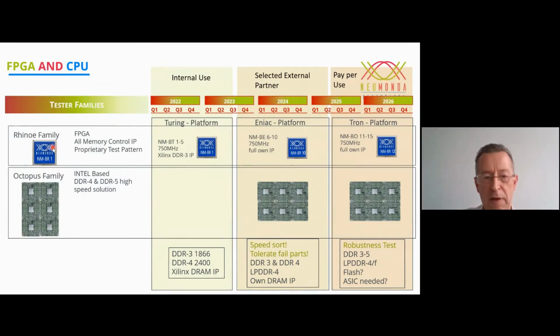If you do motherboard testing with a CPU, there is a microcontroller, the memory controller, controlling the memory channel. So the pattern you write, you don't know exactly what physically happens on the DRAM. So you lose control of the physical pattern on the DRAM. So with FPGA, you can completely control it.